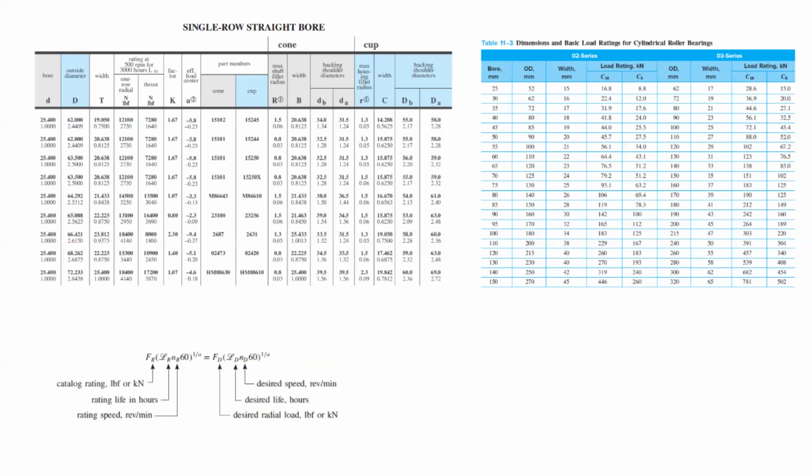And there are also other weird considerations you have to take into account. There's actually a relatively high amount of bearing losses that you get just in terms of energy on your vehicle. When you have your wheel rotating so quickly over such a large duration, the amount of damping forces from the grease in your bearing actually scales with the velocity squared, right? So you can lose a lot of energy from the bearings themselves.